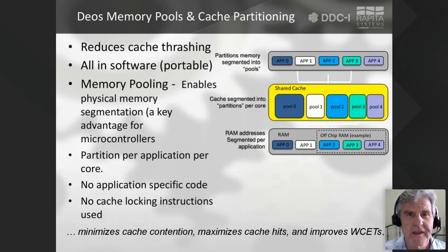In other words, when the execution units in App 0 are not executing, their state is not changed. When they execute again, the cache state is the same as when they left. This maximizes the hits and minimizes the contention. In fact, with this depicted integration, the contention is isolated to the execution units in each application themselves, since each one is dedicated to a specific pool. Since you know your applications, this can be a significantly simpler analysis than if multiple applications were integrated and allowed to use memory that hit the same cache lines.